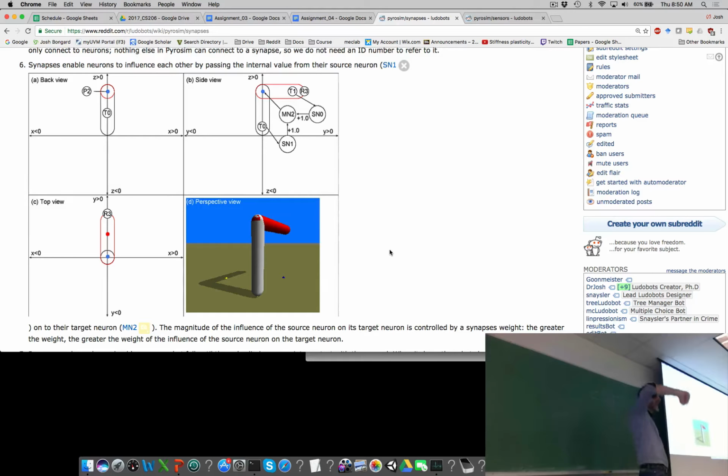The moment there's that sudden acceleration inward of the red joint, the red cylinder, the moment it touches the ground, it springs off the ground, right? And at this point, our intuition breaks down, right? It's not clear whether both of them come off the ground, the red one comes off the ground, the white one comes off the ground. One or both are going to come off the ground, which means the sensor values are going to change, which means the signal that's being sent to the joint is going to change, and now it's going to suddenly change how it's moving again.